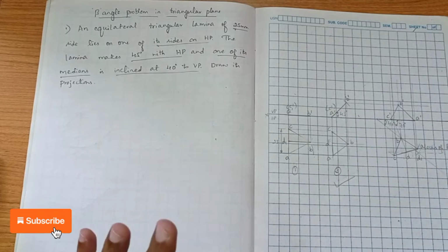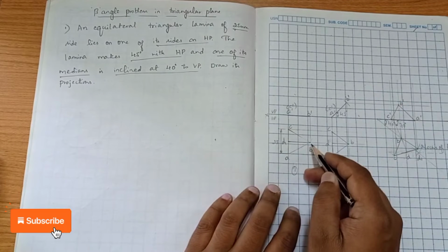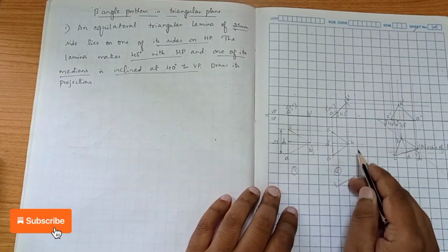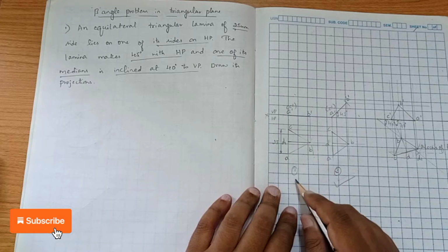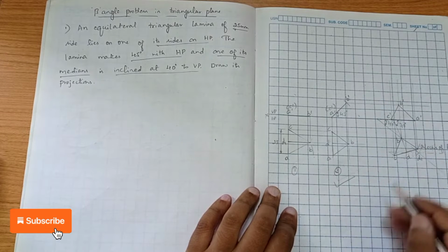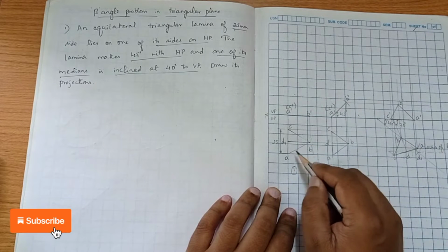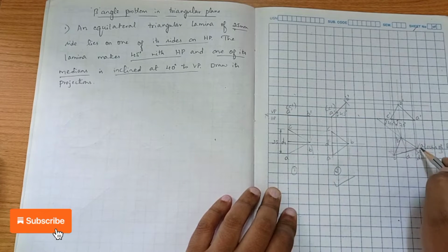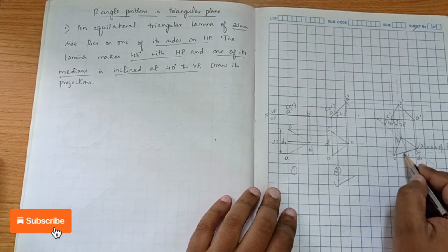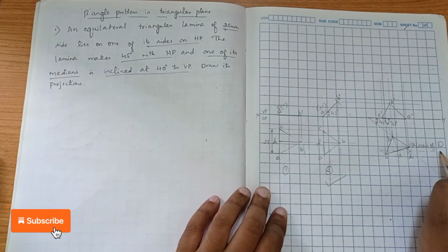So you understood the procedure, right? After constructing these two positions, we have to draw the median, that is BD1, the first median, and BD. So this is the first median, this is the second median. So we draw a 40 degree angle line. After that we mark a point B. First we will measure BD1, this median length, and cut the arc. After getting the arc on this 40 degree angle line, we will draw a locus. We mention it is the locus of D.